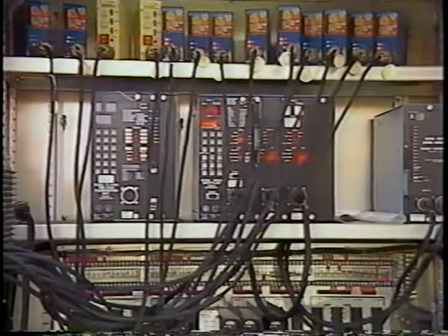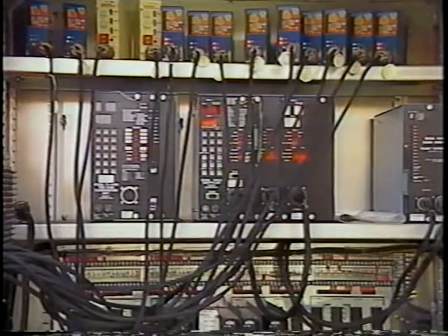For example, loops receive a voltage surge whenever lightning hits the ground nearby. Back-to-back Zener diodes or metal oxide varistors usually provide adequate protection from these surges.